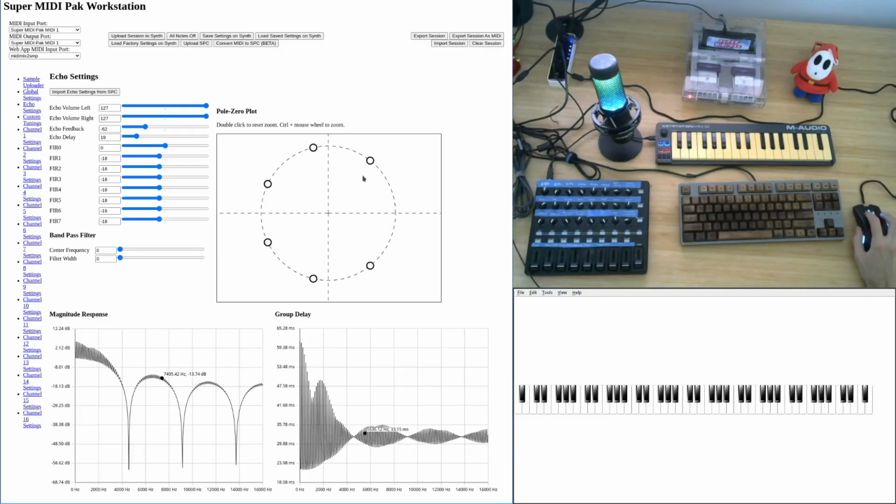And there are very, very many of them; even when the delay is a small value, there are more than 500. And so the effect of this is that when there are very many poles near the unit circle, the magnitude response gets very spiky. It gets spiky wherever there's a pole, because remember, the poles cause the magnitude response to increase. And so the sound that you get when you have a feedback and a delay is this kind of robotic type sound.